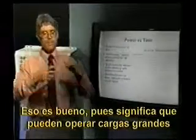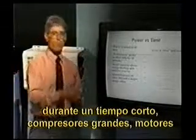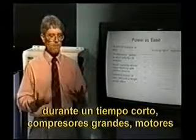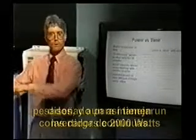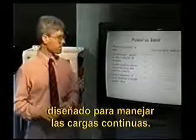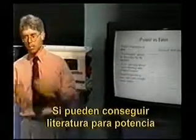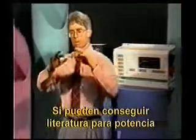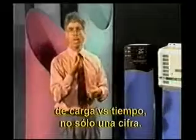That's nice, because that means that you can operate some large loads for a short amount of time, large compressors, heavy motors for a short amount of time, and yet have a 2,000 watt inverter designed to handle your continuous loads. So if you can, try and obtain manufacturer's literature for load power versus time, not just one number.